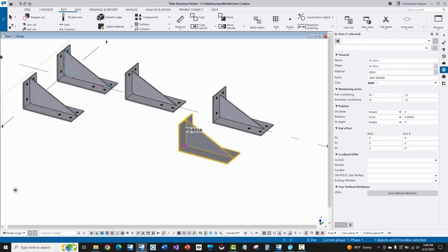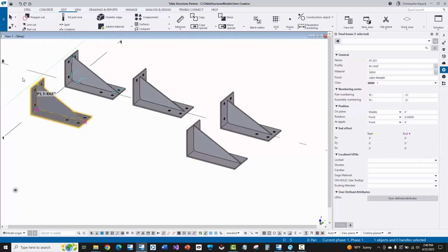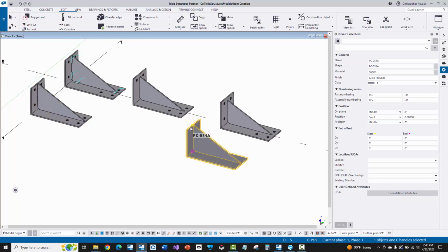Now to actually insert this in, when I click on it, you'll notice that on this particular shape the two insertion points here are actually shown as vertical. Whereas really when I put this in the model, I want it to be horizontal. But the reason why the shape geometry insertion points and the coordinate system of that shape geometry that Tekla created is vertical is because I created the first part on this clip as a polybeam. And when you do a polybeam, you have to pick 3 points. Well, the first 2 points on a polybeam are actually the local coordinate system of that part. And I picked from the top, then to the heel at the corner, and then at the other toe of the leg of that bent plate. And these first 2 points are what I picked, and that's why the shape geometry is vertical.